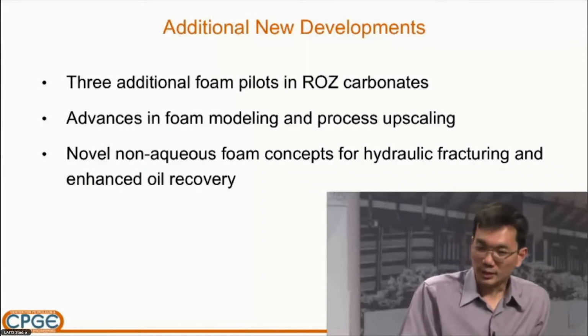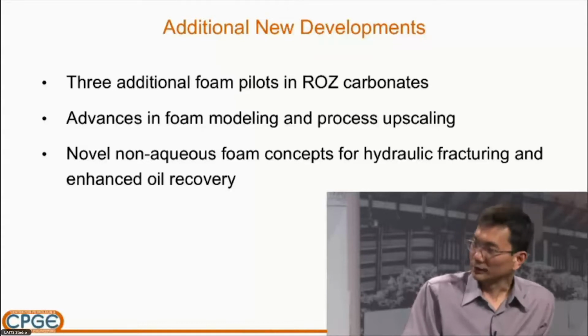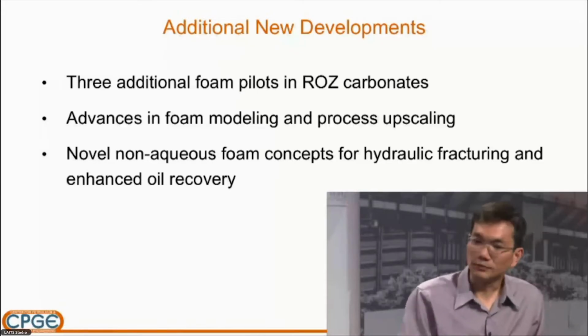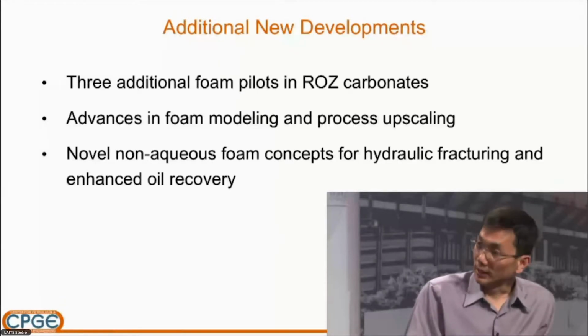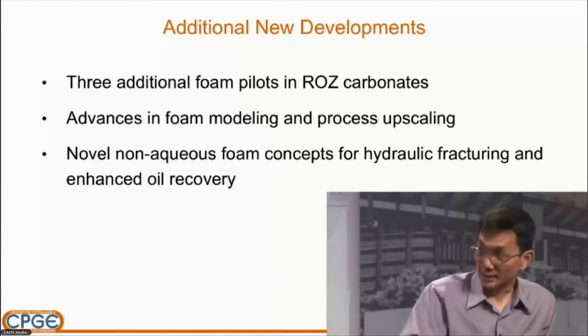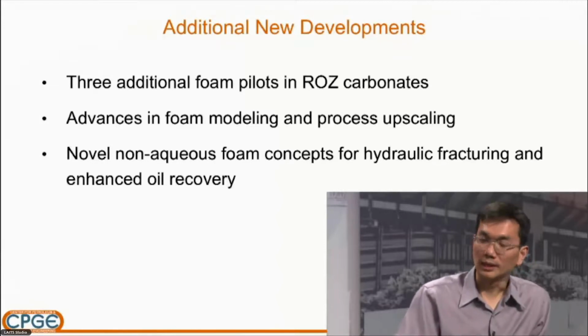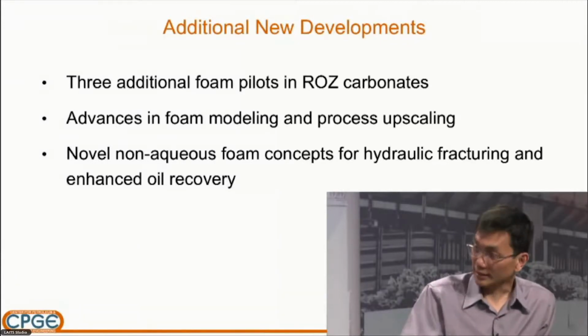Recently, for example, we are using methane or even hydrocarbon gases with a distributed carbon number for controlling the mobility, not just the hydrocarbon gas phase in the gas flooding, but also to control the liquid hydrocarbon phase that is injected, through foaming for improved volumetric sweep efficiency.